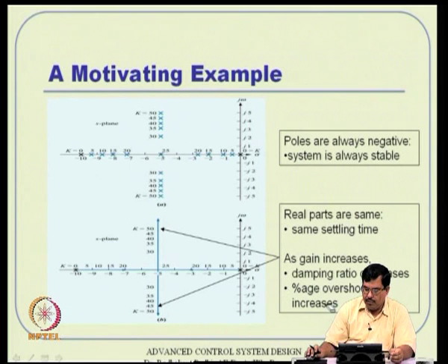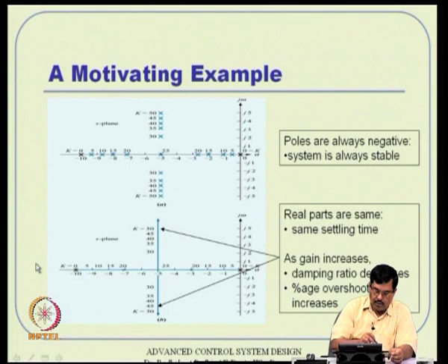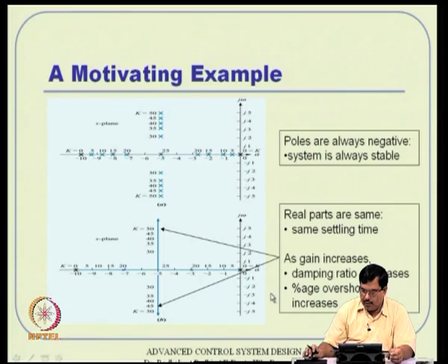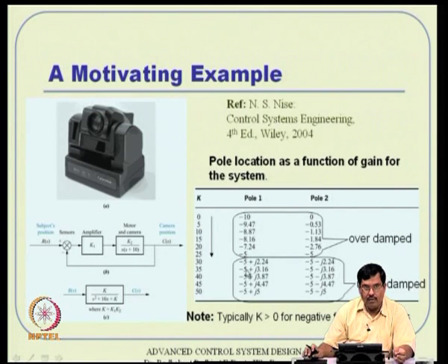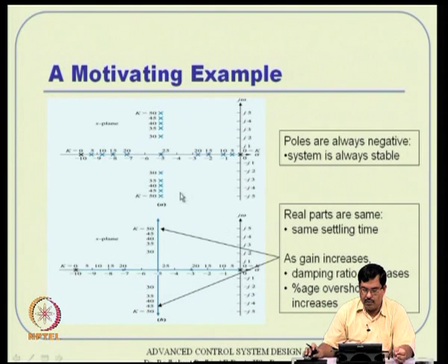Okay. So, the damping ratio starts decreasing actually. And for the same time, the percentage overshoot starts increasing also, because the pole locations go that way. So, essentially what we have done, we started varying this gain k, then we started plotting these values, and then we joined these points that came across, and then it gave us a lot of qualitative information actually.